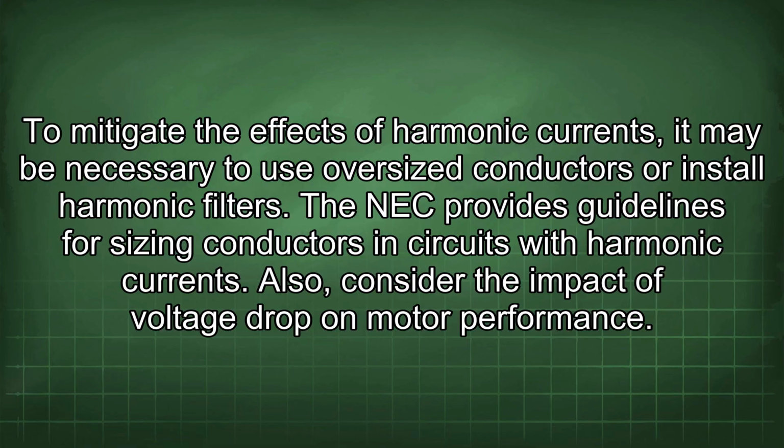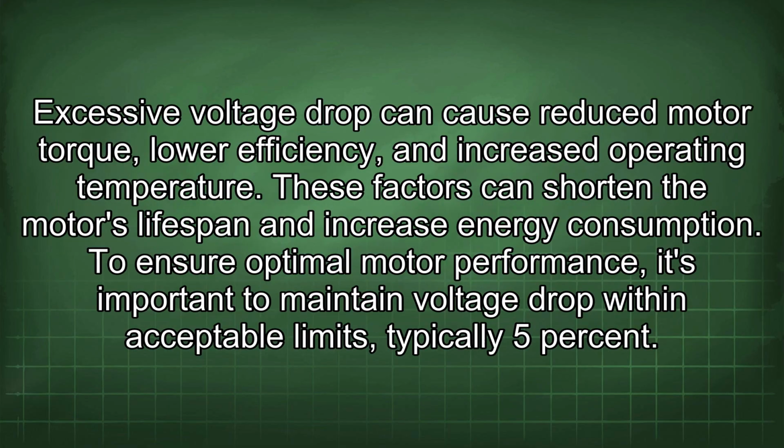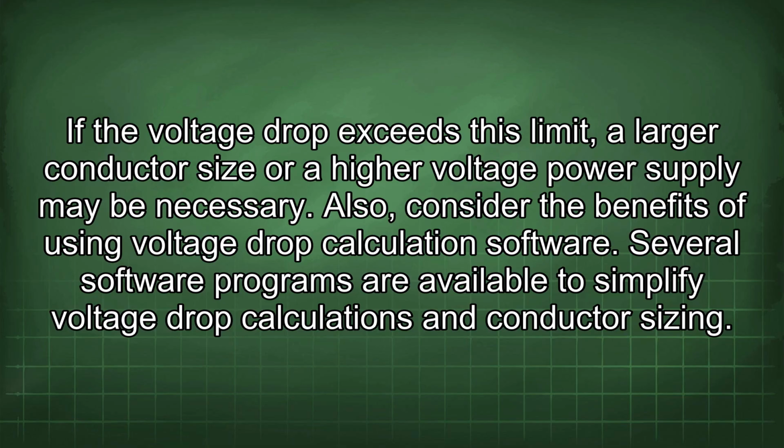Also, consider the impact of voltage drop on motor performance. Excessive voltage drop can cause reduced motor torque, lower efficiency, and increased operating temperature. These factors can shorten the motor's lifespan and increase energy consumption. To ensure optimal motor performance, it's important to maintain voltage drop within acceptable limits, typically 5%. If the voltage drop exceeds this limit, a larger conductor size or a higher voltage power supply may be necessary.